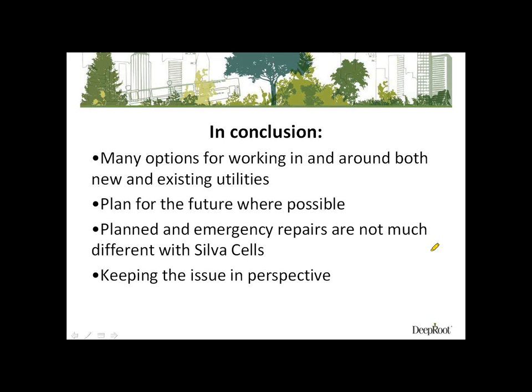Can I just follow up one thing on the geogrid? We have a list of recommended or approved geogrids, and we've spent a fair amount of time trying to optimize the aperture, or the size opening, in the geogrid. Excuse me.